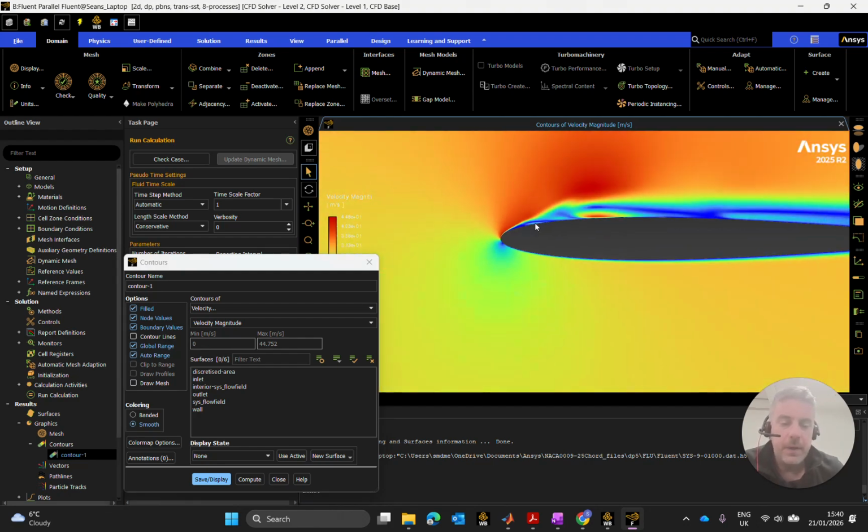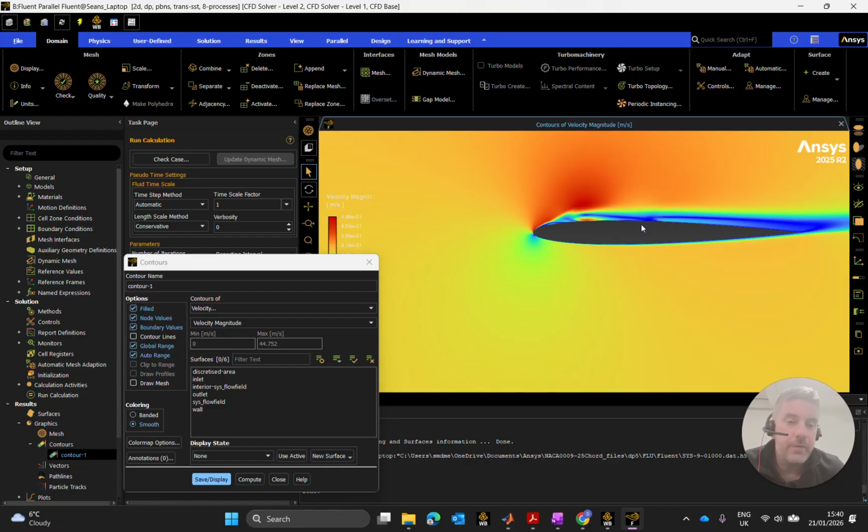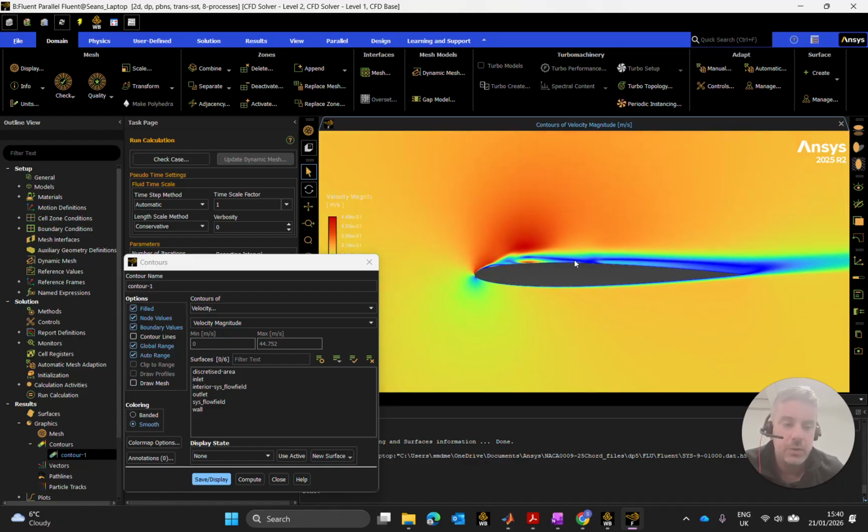So what's happening here now clearly is we're only at a Reynolds number of 50,000, and the big angle of attack isn't just working with it. The big massive separation here at the back. The drag is absolutely huge on it. And you're probably starting to get into stall characteristics here because there's not enough energy in the free stream to keep the air that's rolling over the airfoil here energized adequately.